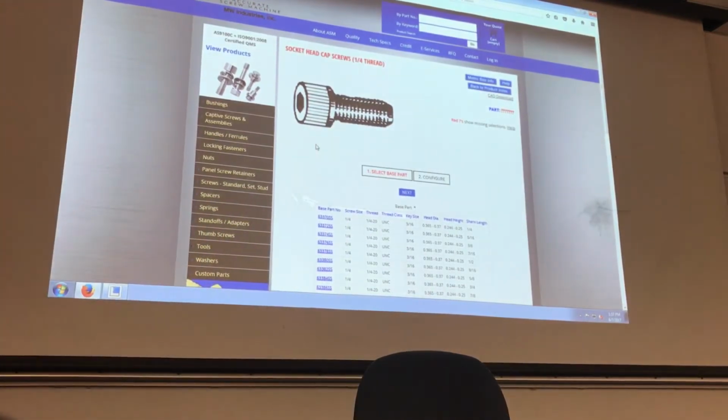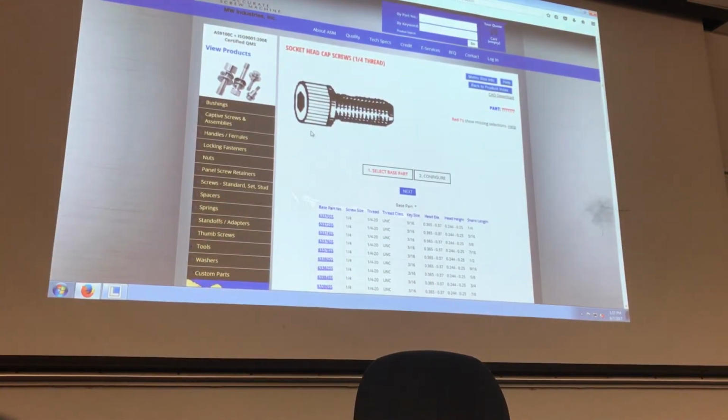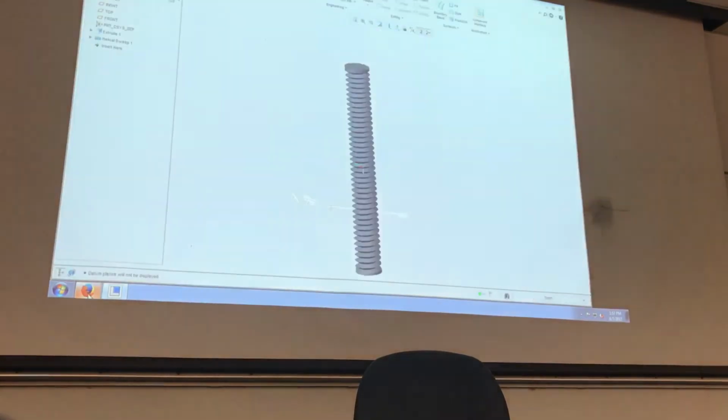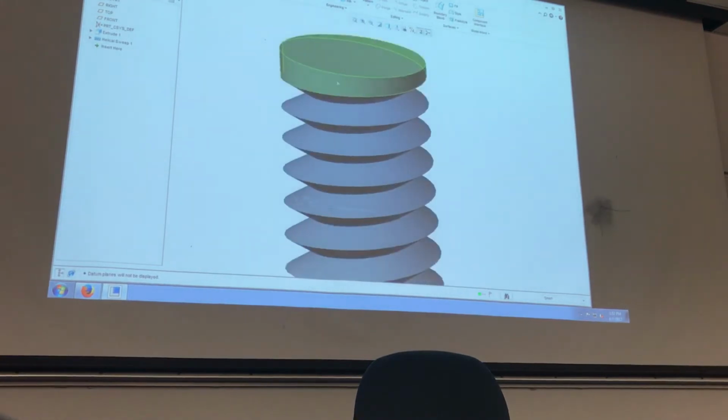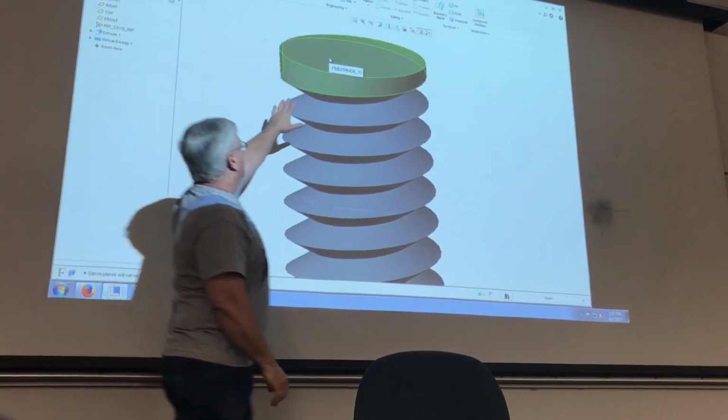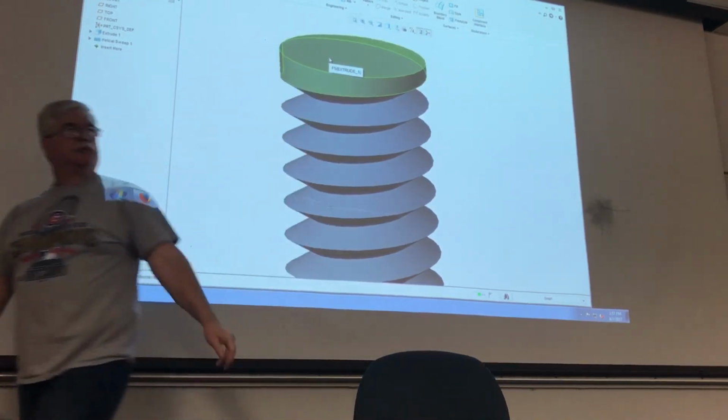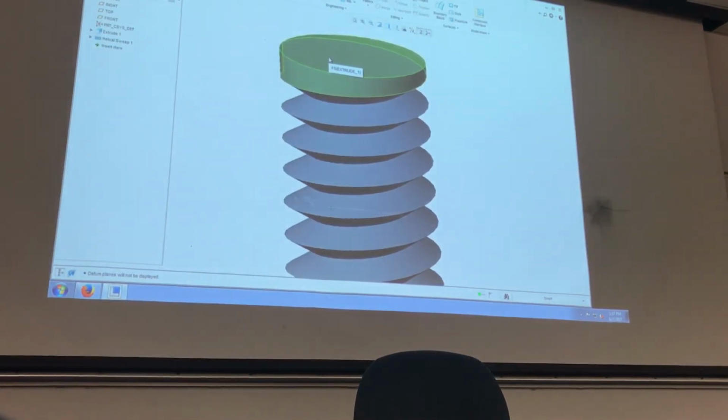Okay? If I go ahead and extrude the head onto this surface here and go up, I won't have a completed thread here. So when I extrude the head onto here, I'm going to do it from that surface and go down into the threaded section, and that way it absorbs this area where it's not complete.